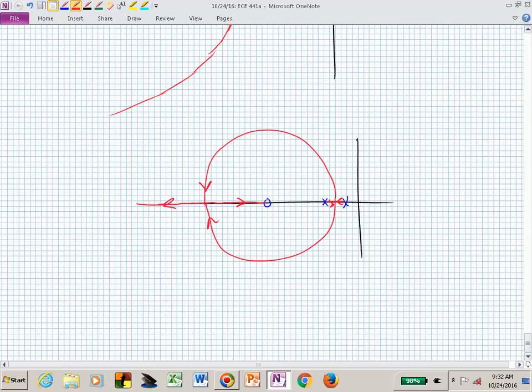Are there questions about this root locus pattern? And that's just one. But in this case, will the system become unstable if I crank up the gain k in a positive manner? Will my system ever become unstable? No. In this case, my system always remains stable. There are systems where if you crank up the gain k enough, you will drive your system unstable. The closed loop poles will migrate into the right half plane. And your root locus branches will show that. They'll be going off to infinity, and they'll be going off to infinity in the right half plane.